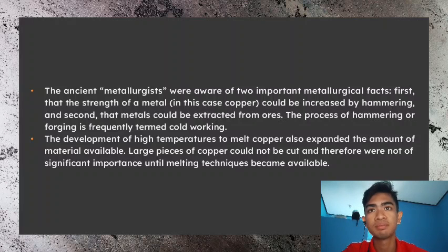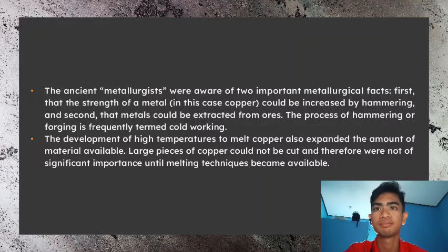If the process shaping was conducted at elevated temperature, the strength of copper was not significantly increased. Thus, metal fabricated at elevated temperature had different properties than metal fabricated at low temperature. This difference in the behavior of a metal processed at elevated temperature and that of a metal processed at near ambient or room temperature remains an important factor in the shaping of metals and alloys today.